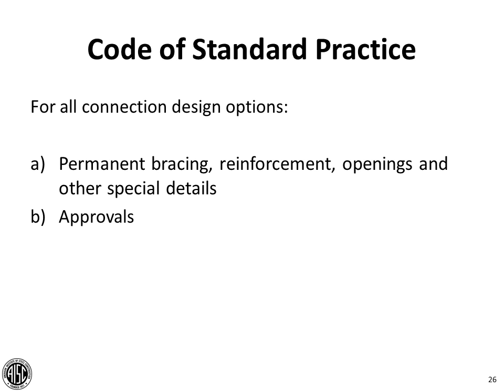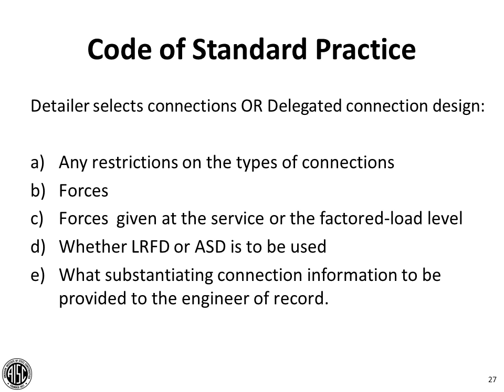So as engineers, we need to clearly and completely show the requirements for the project in the contract documents, the design drawings, and the specifications to make sure the contractor can figure out what our intent is. But then ultimately the approval is that check to make sure that our intent has been conveyed properly and interpreted properly by the contractor. So every once in a while we get some questions where people want to sort of skimp on the approval process, and I would recommend against doing that, and doing so is not consistent with the Code of Standard Practice.